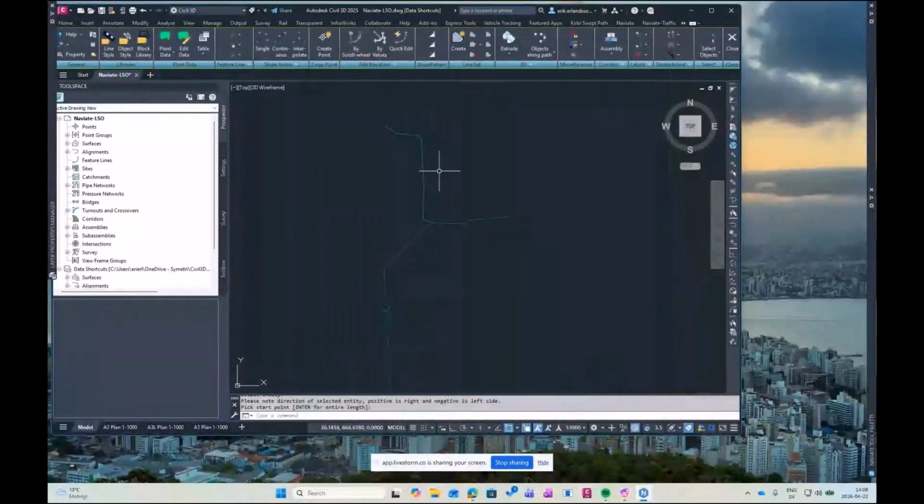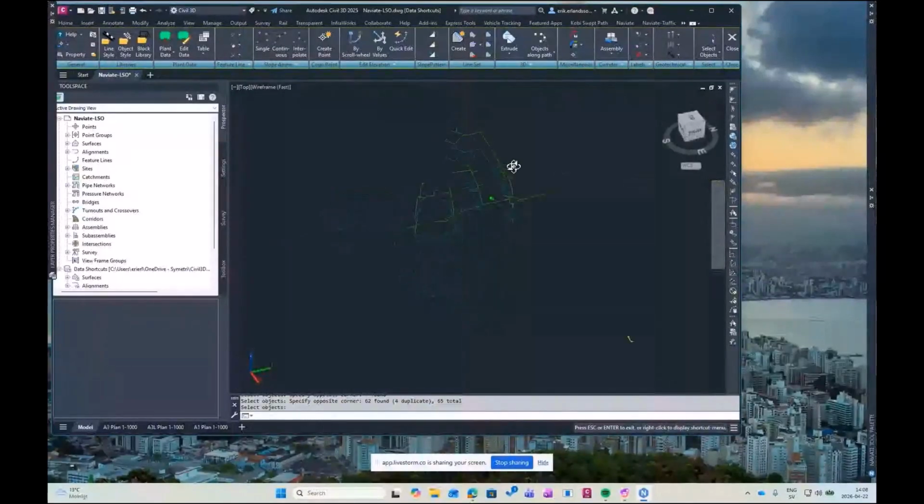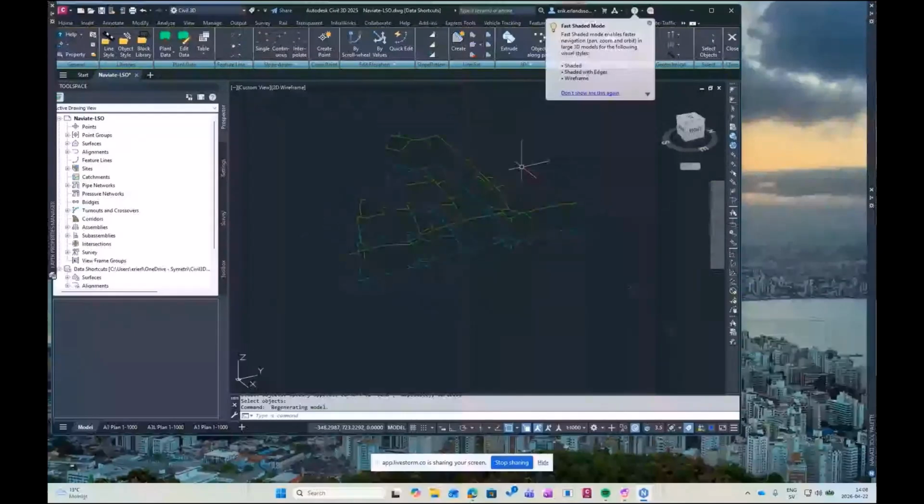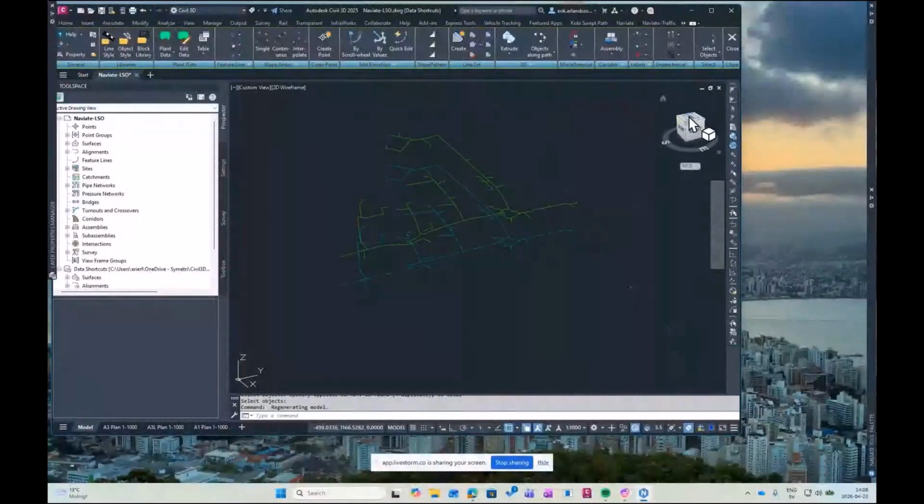And if I click here now, you can see I have my 3D polyline. I will go to copy line set, select my 3D polyline, and then I'll click multiple and select all of these lines and press enter. As you can see, the program works through this area and creates the lines I want. If we flip this up like this, you can see we now have the lines that we want to create the pipes from. So if we go back to the top view, we will go to extrude.